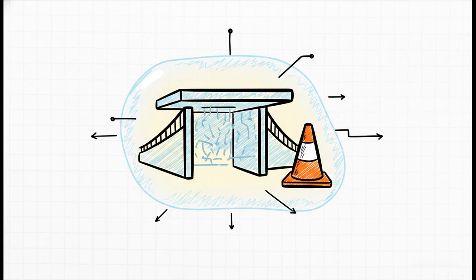Latches are a very specific type of memory that are level sensitive rather than edge sensitive. While they aren't used quite as frequently in modern synchronous designs, having a dedicated block for them is crucial. It means engineers can safely implement latch-based designs without the software accidentally confusing them for standard flip-flops, which, by the way, is a classic cause of really nasty hardware bugs.